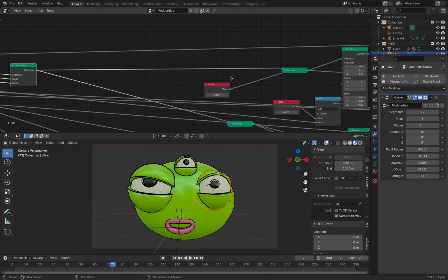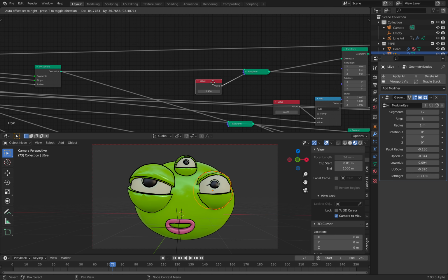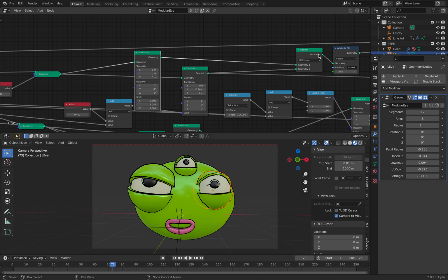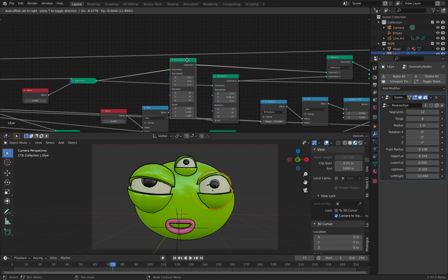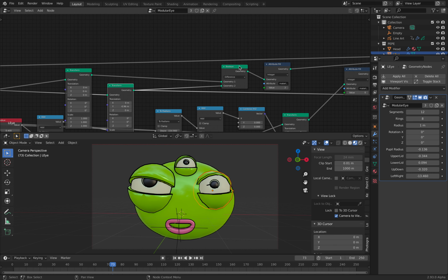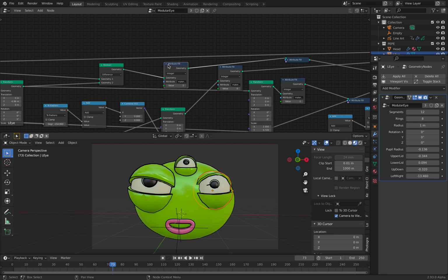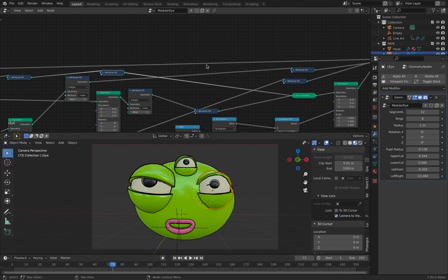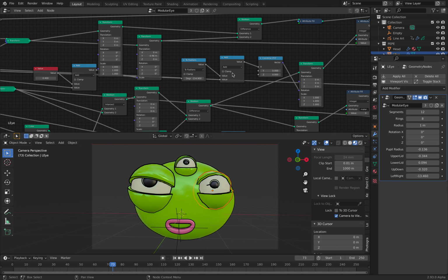I should mark it. And then whenever this goes into a transform, I can control it, I can scale it, etc. just so I can Boolean it later with another transform. So it's really important: transform before Boolean. I make a difference, and this one is just to assign a material, and this one just to make it smooth. So that's not very important. This makes the eyeball.